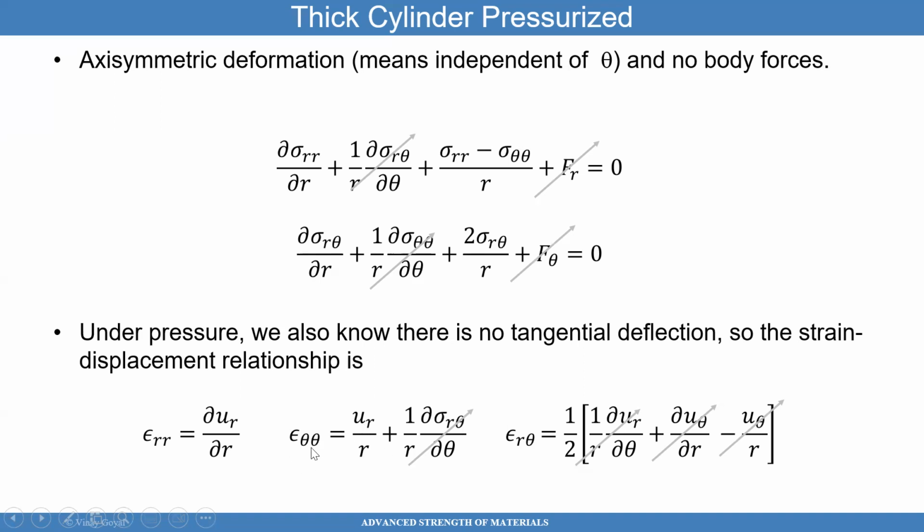You can think about this: if I take a pressure vessel, a cylinder, and I expand that cylinder, you can imagine that there's a strain in the circumferential direction reacting to that thing wanting to expand radially out. So think about that carefully. Put a rubber band around a cylindrical shell in your head.